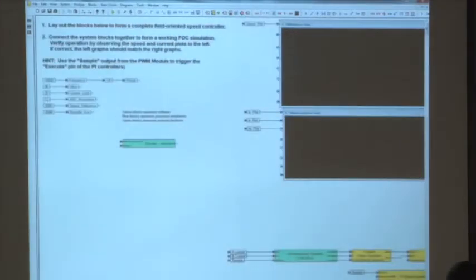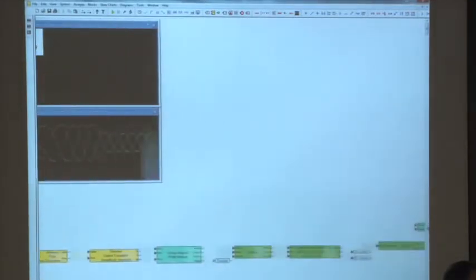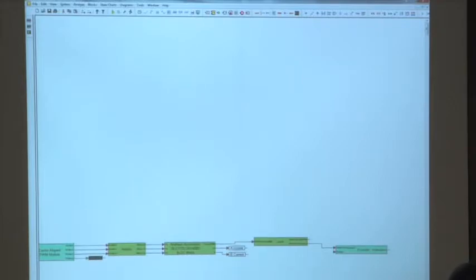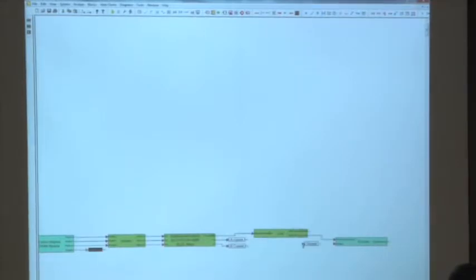The position, I'm actually going to run through an encoder simulation first before I feed it back into my algorithm. So grab the last remaining block, which is the encoder block, and take the shaft position and put that down into the shaft position input on the encoder. You can also see that the encoder signal needs to be sampled. So we're going to find one of those sample signals again, select it, Control-C and Control-V, and paste that on the input of the encoder module.